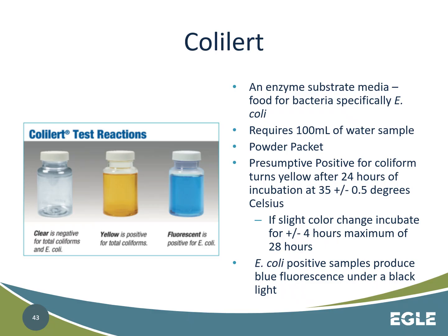The lab is then going to add the powder pack of Colilert media to it. They're going to shake it up until it fully dissolves. The water was clear and will have a little bit of a cloudy tint to it, but nothing too significant. Then it'll be placed in the incubator for 24 hours. The incubator is at 35 plus or minus 0.5 degrees Celsius. And after it's sat in there for 24 hours, the laboratory pulls it out